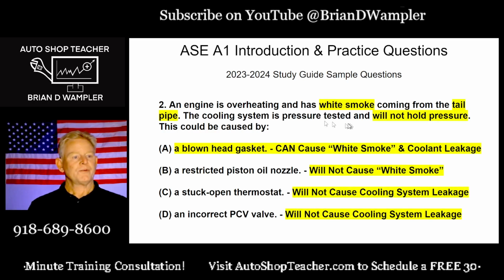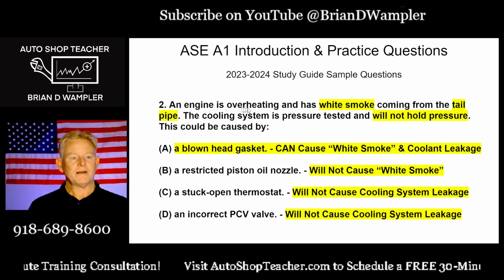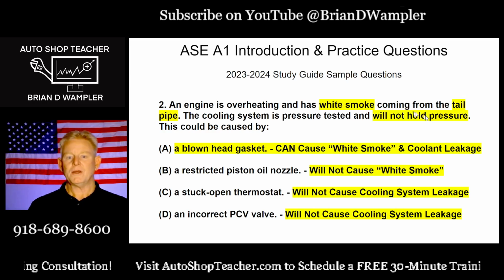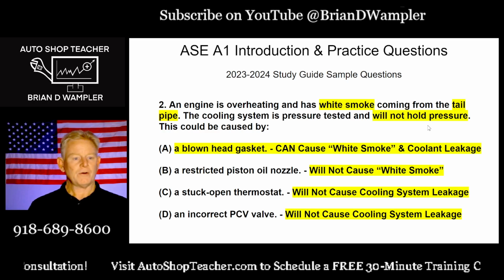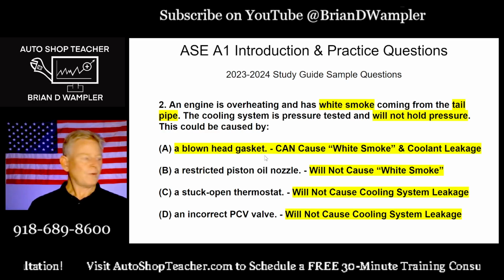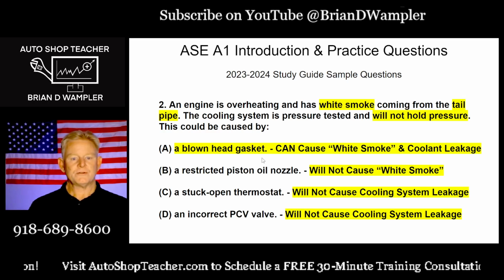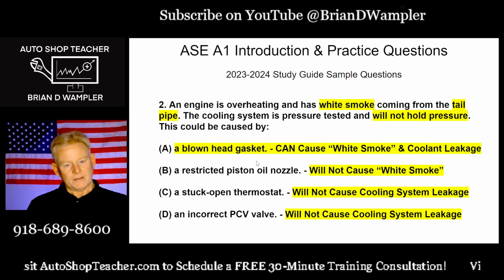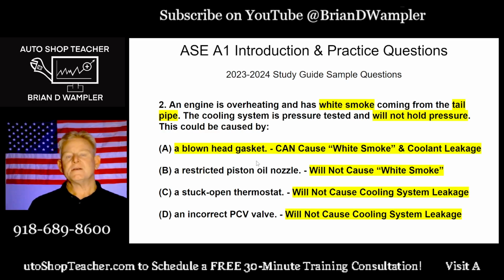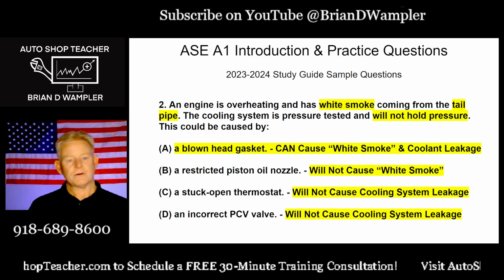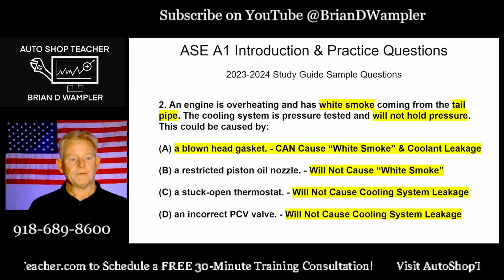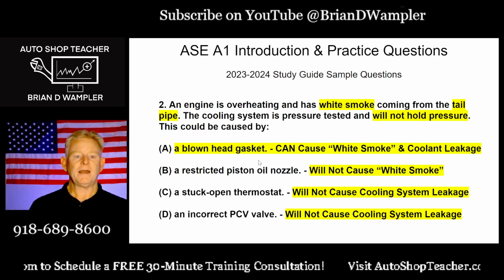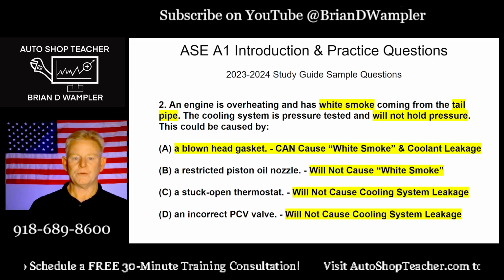Okay. So, as mentioned, I'm sorry I didn't highlight the overheating, but we've got overheating, white smoke, and the cooling system will not hold pressure. So I jumped straight to the answer on this one, but I'm still going to talk about it a little bit with you to help work through the process if you didn't already have your answer as option A before I clicked to this slide. So a blown head gasket, yes, it can cause white smoke and coolant leakage.